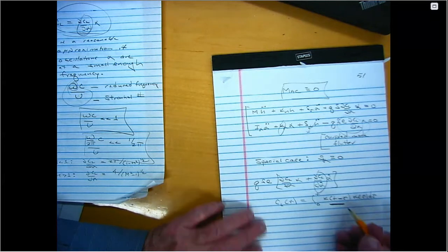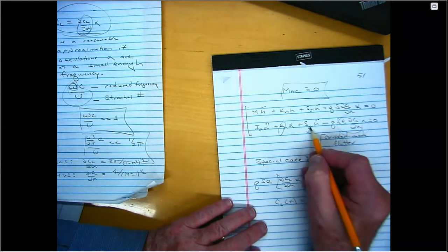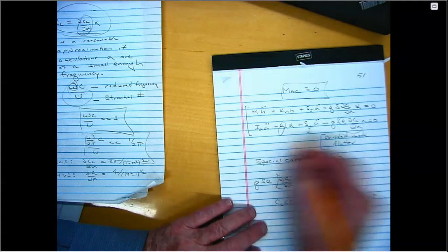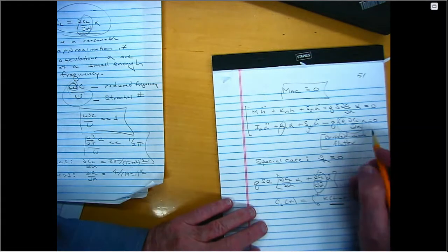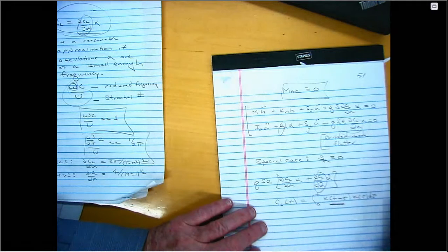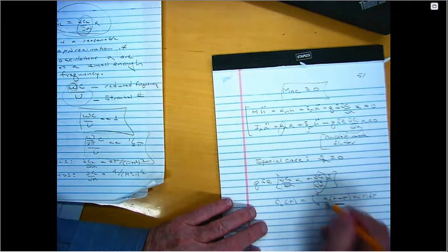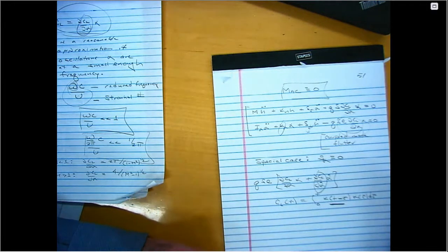But when I use this model, it's not so obvious, at least at the present time, whether the damping is positive or negative. But if I use this, even for S alpha 0, I could, in principle, time march this equation. I could go over to my friendly MATLAB software and run the solution, including this time history, if I know the K function, and find out whether the solution is growing or decaying.